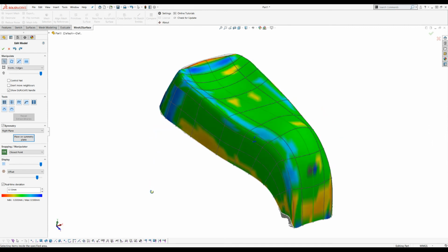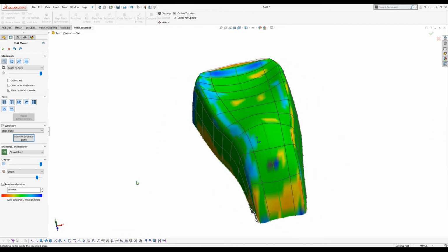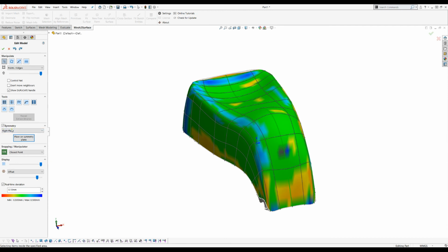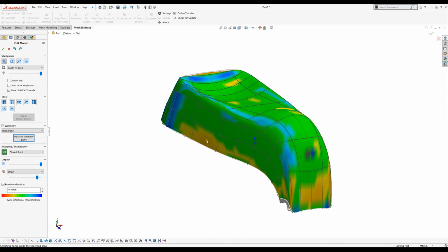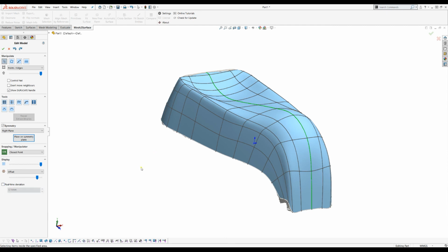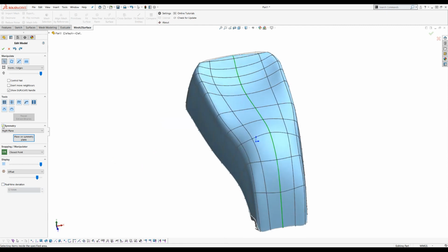And now, before we finish, just to say a little bit more about the application of the symmetry. If we explore this object, we see that everything here is green, but on the other side, it's not exactly within tolerance. But I must say that it's asymmetrical. So now the question is, what do you want? Do you want to get as close as possible to the surface of the scan data, or do you want to keep the symmetry? And this is where our symmetry option comes in.